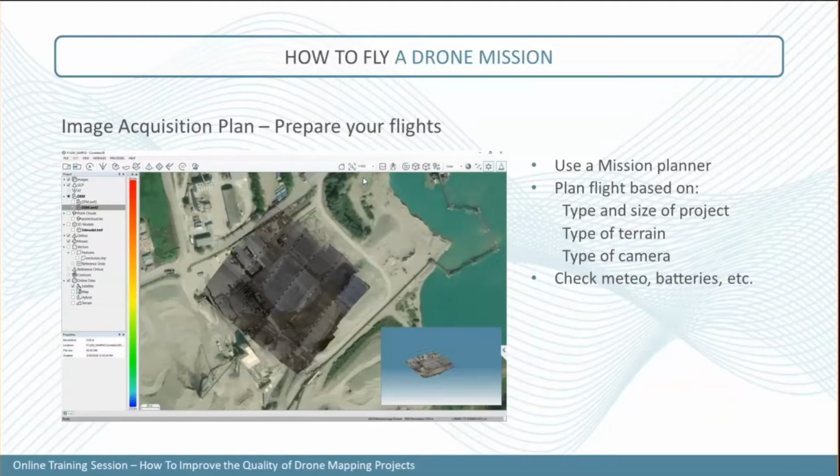One thing that's also really important is the time when you're going to fly your project. Make sure that you're flying from 10 a.m. to 2 p.m. That should be the timeline you target if you want good weather conditions, because you don't want too many shadows during your acquisition, as those may impact the output of your mapping product. Also, you want to be as close as possible to noon. You don't want too many clouds. You want light that's quite homogeneous throughout the flight.